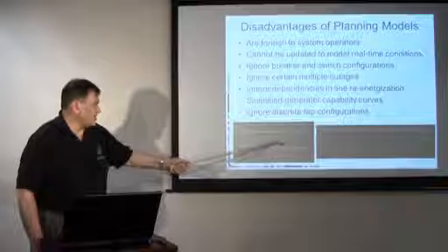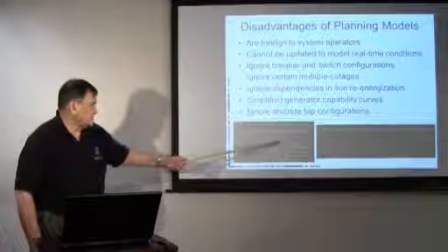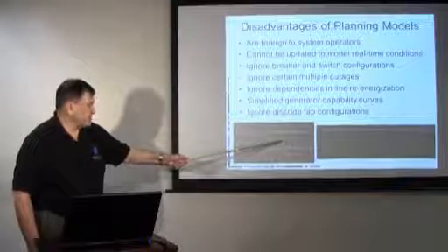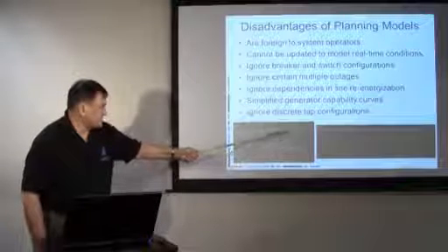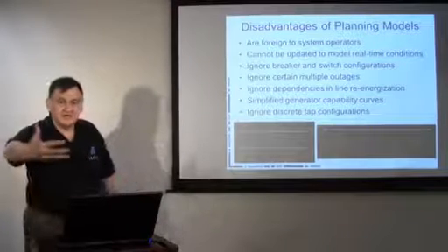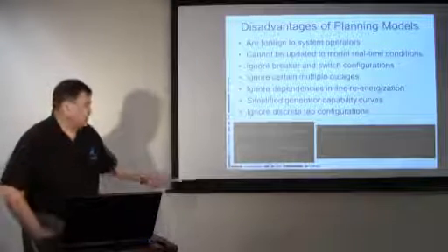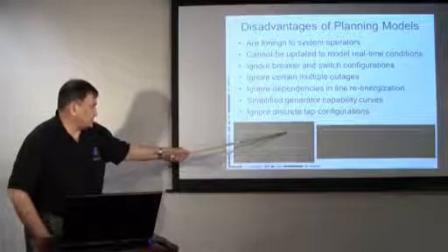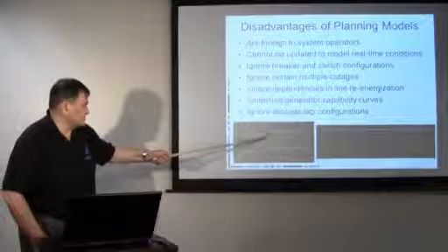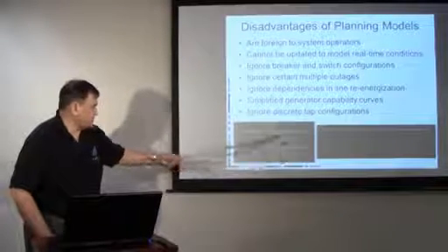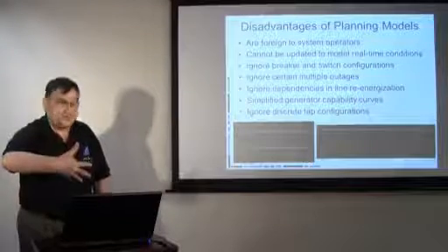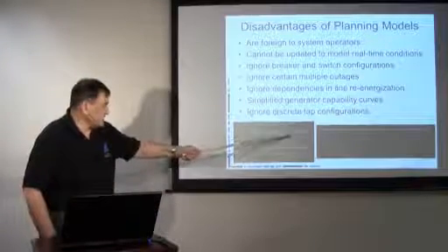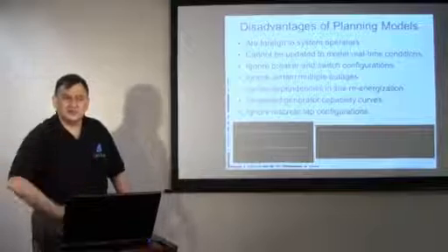The only way I can get to this line is I close this breaker, and in that process of closing that breaker, I'm going to energize that line and have a whole bunch of megavars come in. And then I close this breaker, I heat up the bus, I close this breaker, and now I've come in on this line and I've gone out on that line, which was my objective. But in the process, I had to energize that line and absorb the megavars.